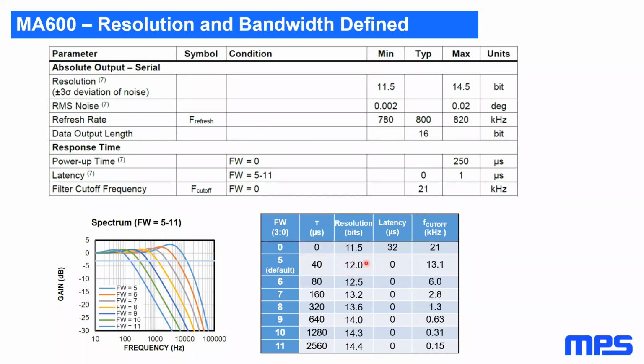For a half bit of resolution, so going from 12 to 12 and a half, the cutoff frequency is halved. A little more actually than halved. And again, that's because this is that TMR part that doesn't have exactly log linear output, but the general shape holds true. And then you can actually see the cutoff frequency at various frequencies.